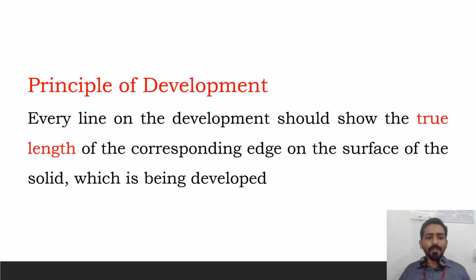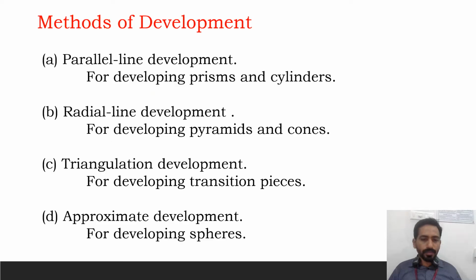Now, the principle of development. Every line on the development should show the true length of the corresponding edge on the surface of the solid when it is being developed. So, you can assure that all the lines which represent the edges will have true length in the development.